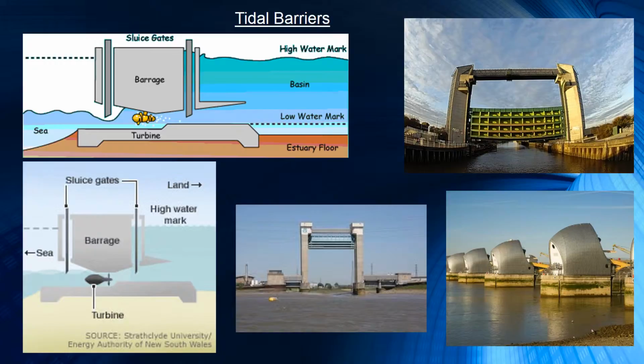Then there's a thing called the two-way tidal barrage scheme. Two-way electrical generation requires a more accurate control of the sluice gates, so keeping them closed until the differential head height is sufficient in either direction before being opened. As the tide ebbs and flows, seawater flows in and out of the tidal reservoir through the same gate system.